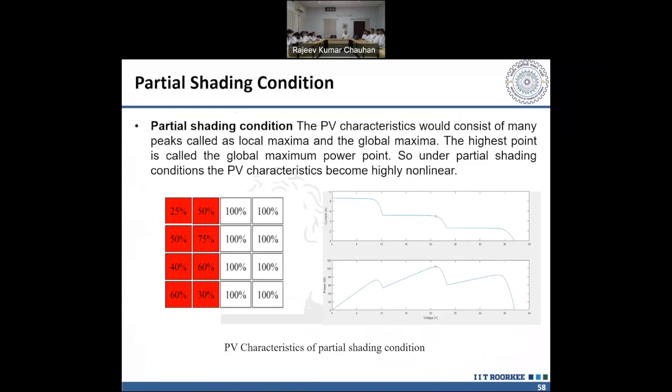So basically what is happening is that at different times you are getting different peaks. We already have this stored. So we will divide the whole into different sections, and for each section we will apply this P&O. Here, then here, then here. And we will see where it is maximum. This point is maximum, so we will select this particular point. By this we will select the maximum power, MPP.